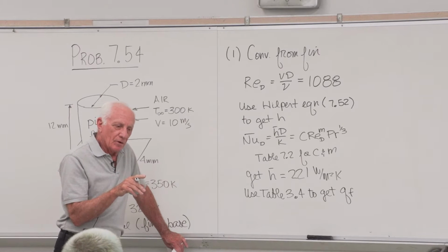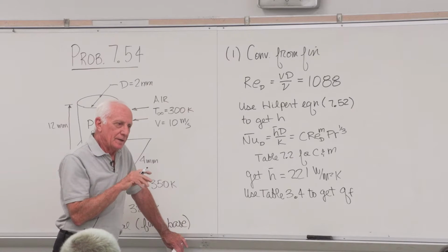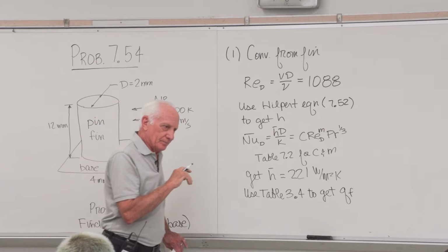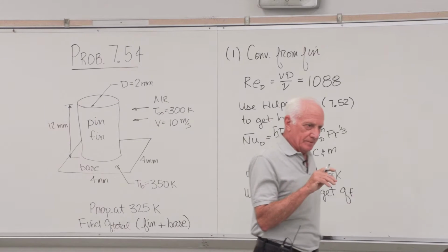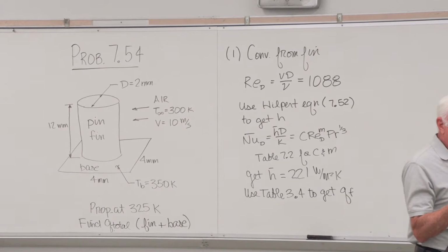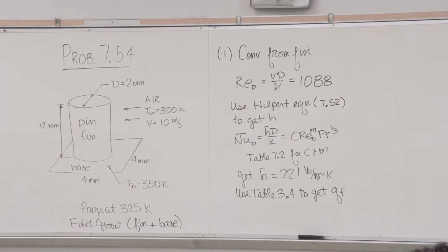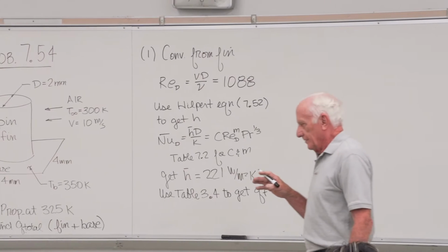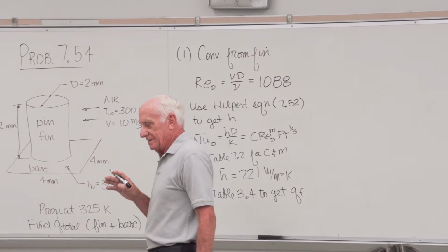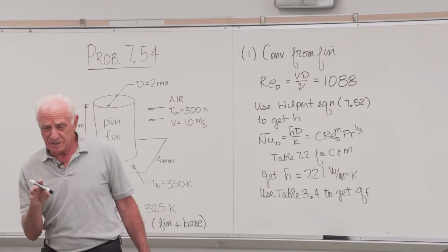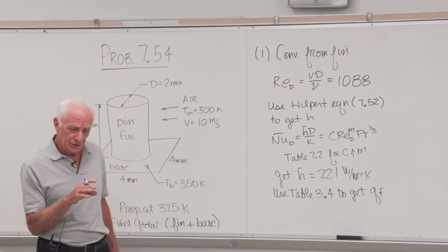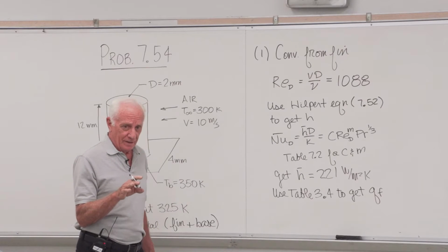In table 3.4, there are 4 options: convection at the fin tip, adiabatic fin tip, prescribed temperature at the fin tip, and the model which says the fin behaves as if it were infinitely long. We said the easy way out is case D. See if it can be modeled as an infinite fin, because q f is ridiculously simple.